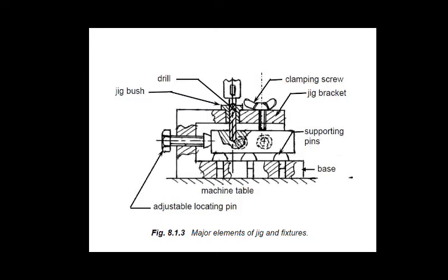The jig body is generally made of cast iron by the casting process, or fabricated by welding together various slabs and bars of mild steel. It may be heat treated to relieve the stresses. The body is the most prominent feature of the jig. Its main purpose is to support and house the job.